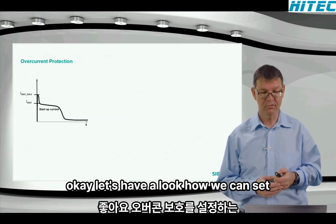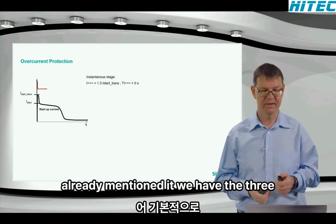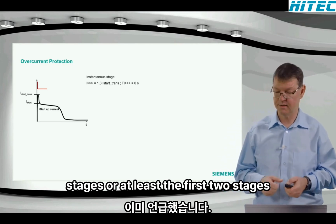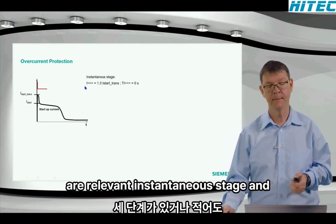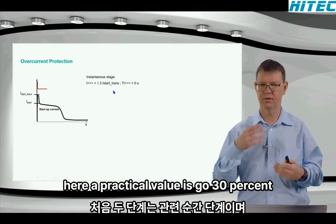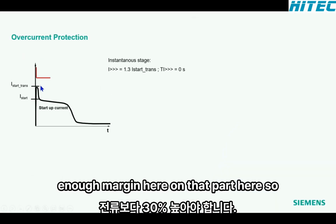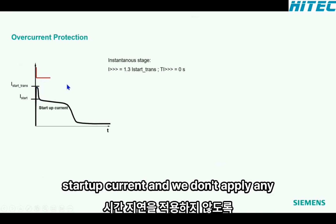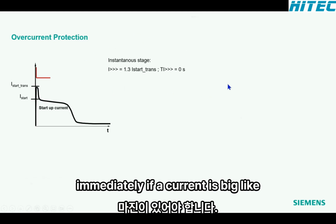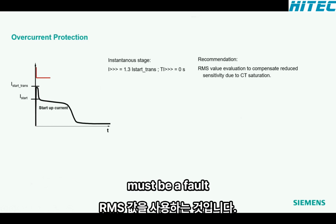Okay. Let's have a look at how we can set the overcurrent protection. Basically, I already mentioned it. We have the 3 stages, or at least the first 2 stages are relevant. Instantaneous stage, and here a practical value is 30% above that transient current, to have enough margin so that we don't interfere with the startup current, and we don't apply any time delay. So here we can trip immediately. If a current is that big, it cannot be something regular, it must be a fault.